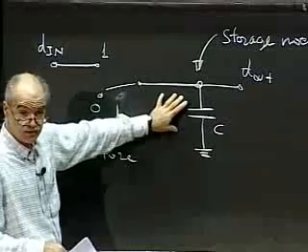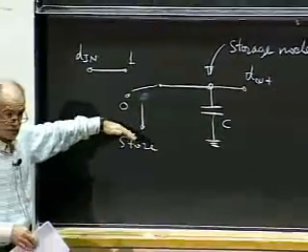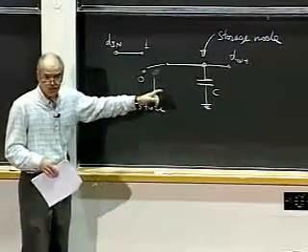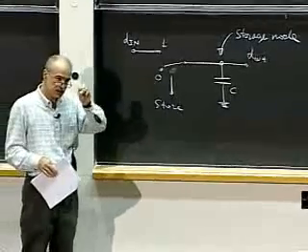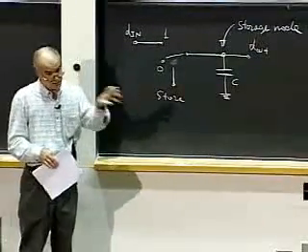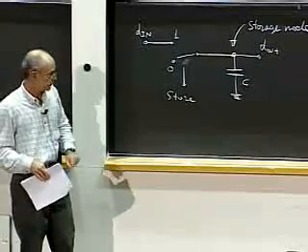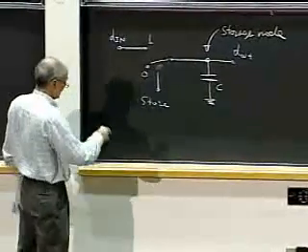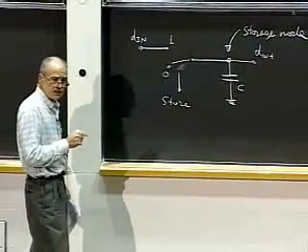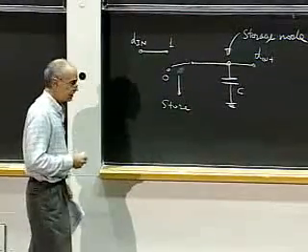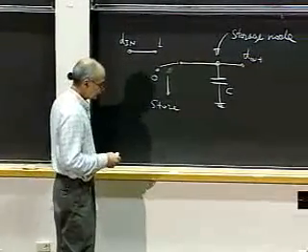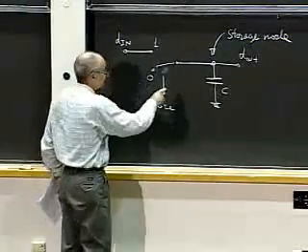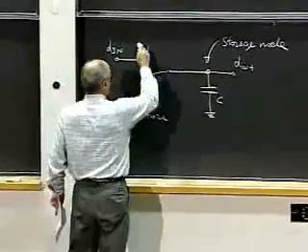Okay, so it does store the value of the voltage that it saw, 5 or 0, high and low. It stores it because it stores charge, okay? So that's actually the physical quantity that is stored. It's manifested as a voltage, which we see. All right, before I move from here, so what is the basic cell in a DRAM? You know, one that you go out and buy by the billions of cells. It's actually this. The only difference is that this switch here is replaced with a MOSFET.